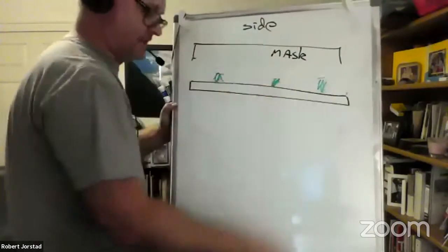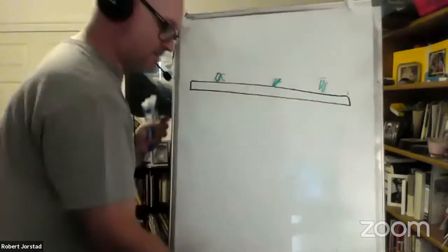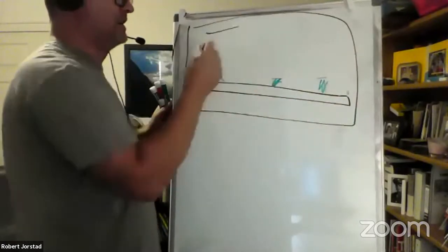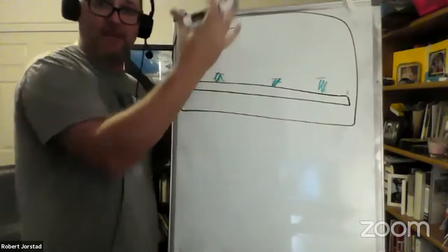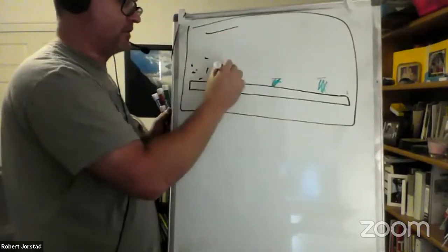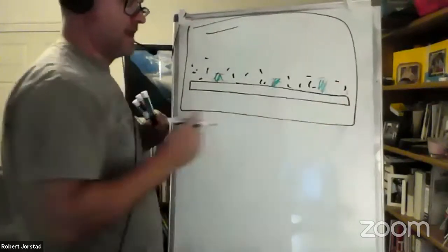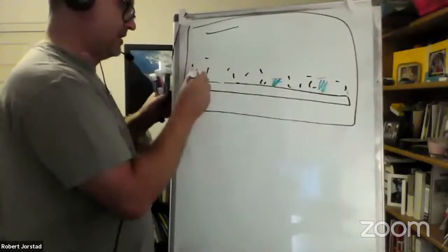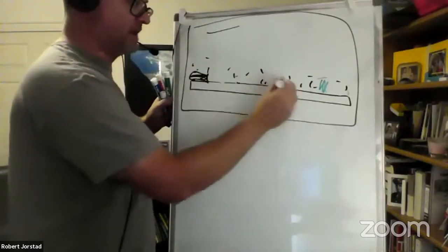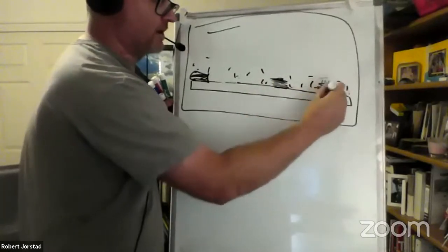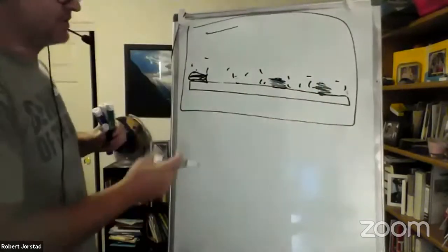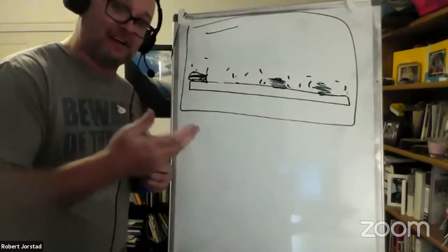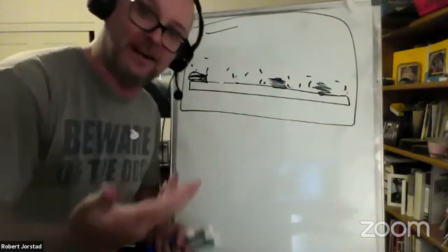But at some point, you take the mask away, then you put this in a bell jar or a vacuum chamber, and you take a hot wire and put a lot of current through it, and it vaporizes. The pieces of metal gradually deposit here, and then you come in and pour some more chemicals on it, and anything here would not have metal on it. So what you've done is you've placed patterns, basically metal forms where the photoresist used to be, or the opposite if you use the other type. This is how you can draw wires and things on chips. And you could imagine calculating the resistance needed using rho L over area and this and that.